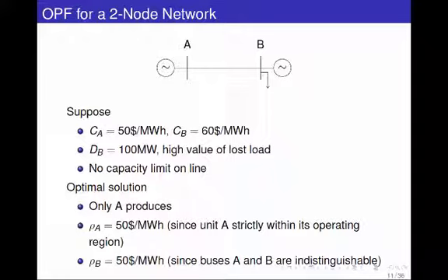So on the one direction, if I make this change in the right-hand side positive, well, if I'm not going to change my dispatch when I'm going from 100 megawatts to 101, the welfare, the objective function is the same. So this is 0. So one valid value for lambda plus is 0. But now I can see it the other way around. What happens if I decrease the capacity of the line from 100 and go down to 99? How are you going to deal with that?